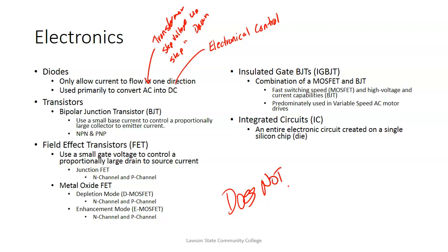It does a little bit, because there's no such thing as anything that's 100% efficient. So the work you put in will never equal the work you get out, no matter what system you go through. You always have a loss inside the system. But the power we put into, let's say, a transformer, if it was 100% efficient, if I put 100 watts in, then over here on this side, we call the secondary, we would get 100 watts out.